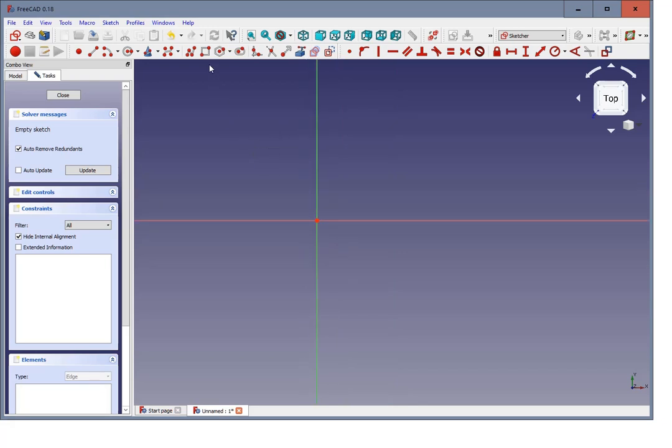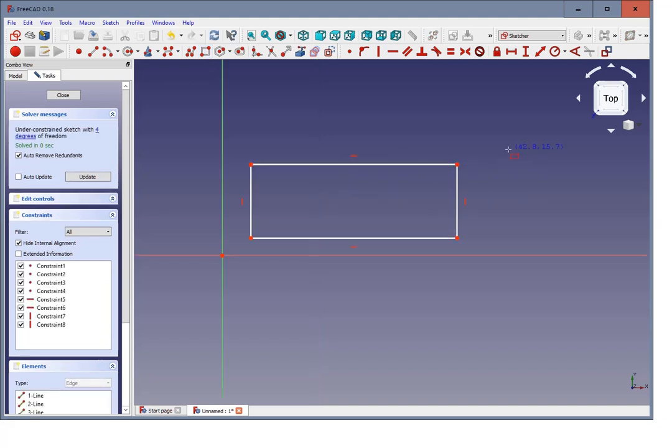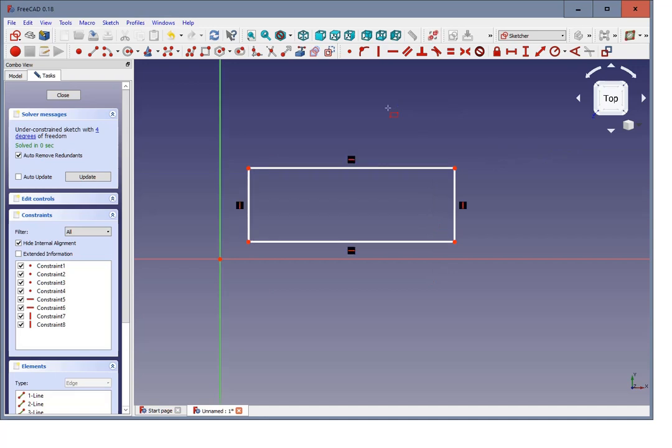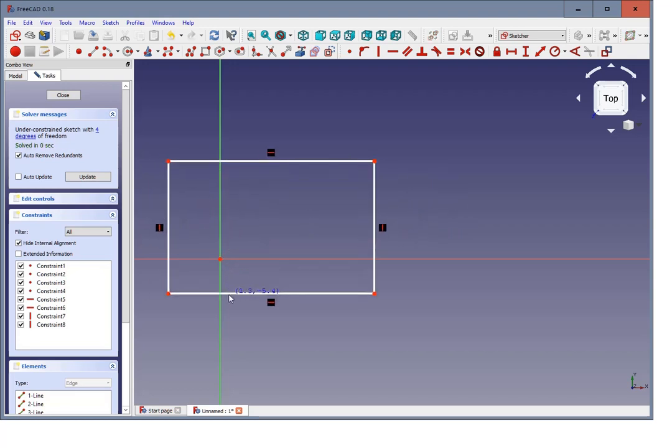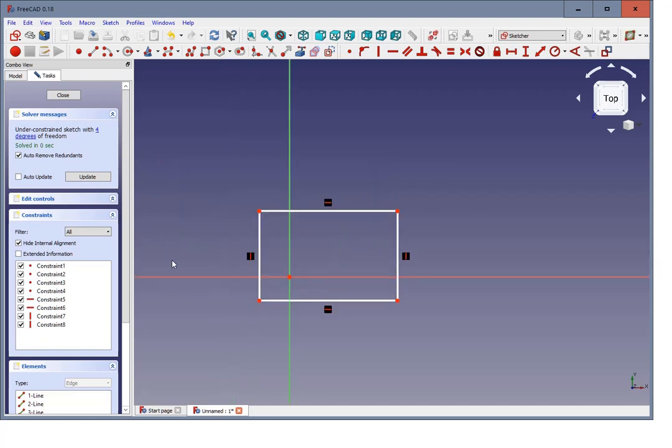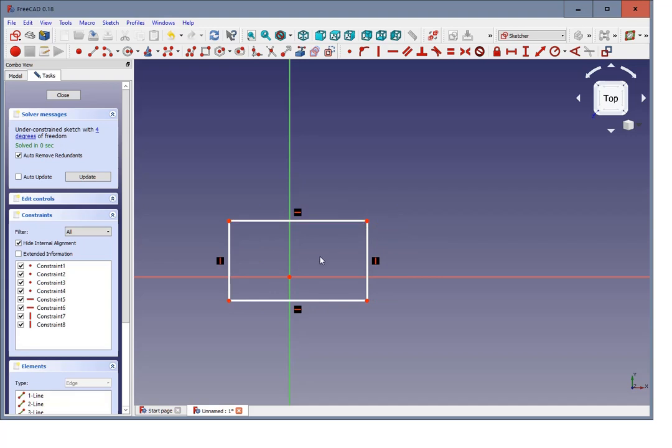Let's create the door frame. The door frame is relatively simple and relatively straightforward. We create a rectangle and we have to fix that rectangle to a reference point. In this case I'm not going to do it in the usual way, which is fix it to the center point by making it symmetrical over the corners to that point.